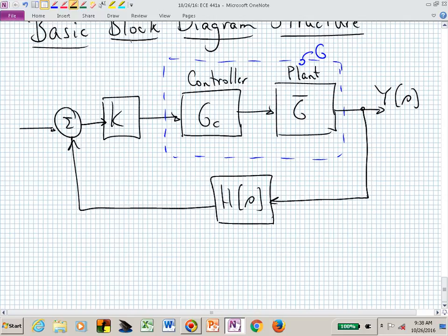And those will then get compared with the reference input. But what I want to do here is, let's say that this is coming in with a positive sign, but maybe we have a negative sign, or depending on who builds this, maybe they've put in positive feedback. So this is then going to be positive feedback. And this one will be negative feedback, and that's the one that we will typically just assume that we have. But depending on whether we have negative feedback or positive feedback, that will influence the sign in our denominator expression, whether it will be a plus or a minus.